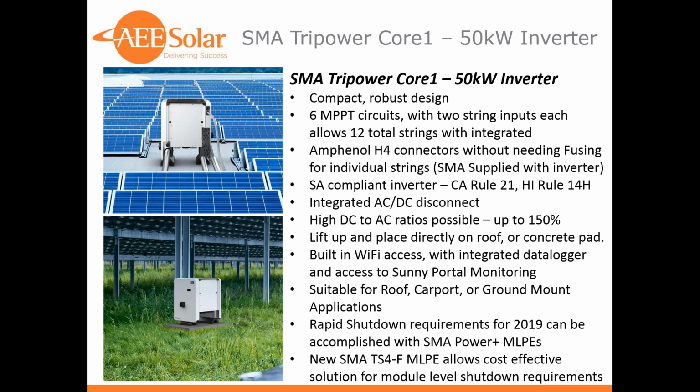So being that it's only 2 strings per circuit, we avoid the need to individually fuse each string, since it's only 2 strings per MPPT circuit. This allows an infinite, really, design flexibility here for number of panels or subarrays. In addition, these inverters have a very wide MPPT window. These things are really, really nice.